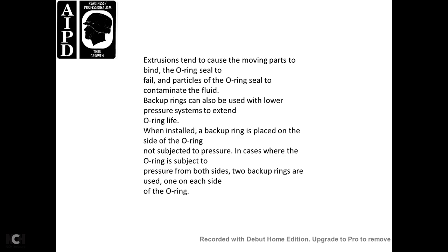When installed, the backup ring is placed on the side of the O-ring not subjected to pressure. In cases where the O-ring is subject to pressure from both sides, two backup rings are used, one on each side of the O-ring.